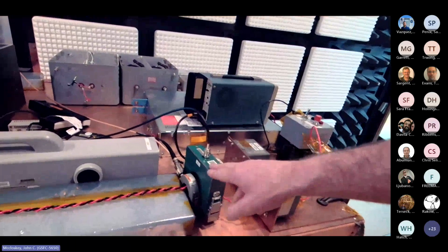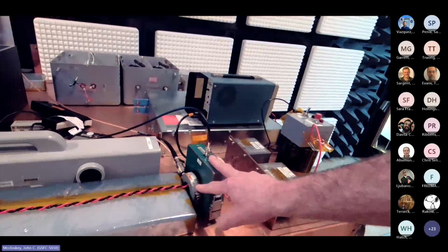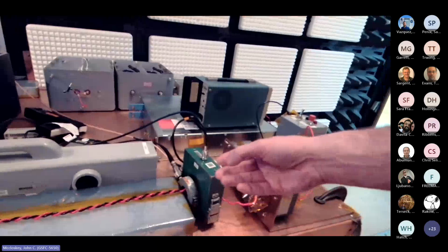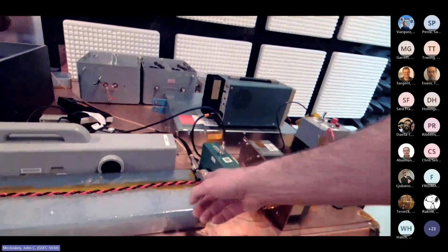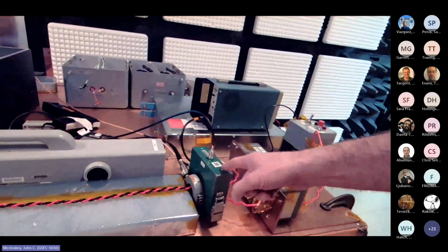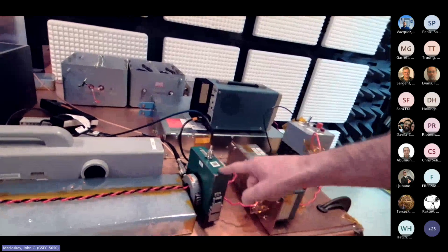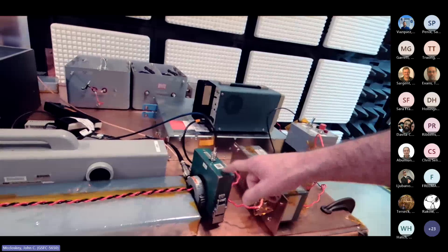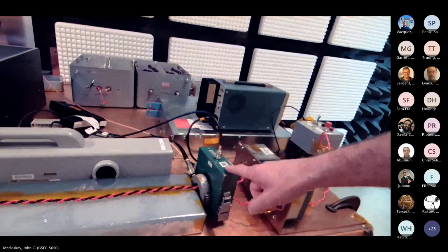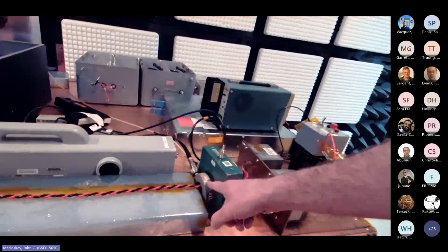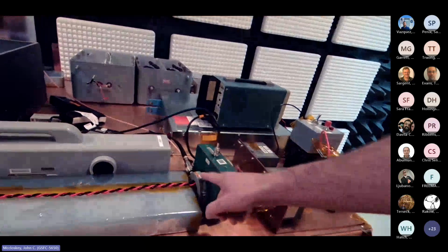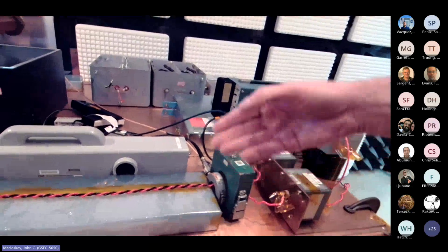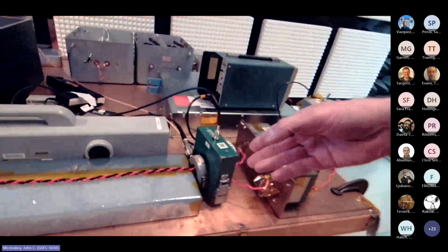When I'm measuring something in the time domain, I like to use both of these probes at the same time and compare what I see on the scope, to determine if the low frequency content is being skewed with this probe, then it's lower frequency stuff that this one is probably going to help me better with. If it's above 10 megahertz and this thing is kind of giving out, and I see a lot more high frequency ripple that I'm seeing more accurately with this one, then all right, I can remove this one and look at everything with this one. So just things to think about when you're making measurements. Again, always just be aware of your test equipment's capabilities.